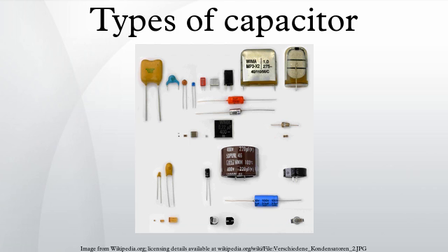The narrow tolerances of E24 to E96 are used for high-quality circuits such as precision oscillators and timers. General applications such as non-critical filtering or coupling circuits employ E12 or E6. Electrolytic capacitors, which are often used for filtering and bypassing capacitors, mostly have a tolerance range of ±20% and need to conform to E6 series values.